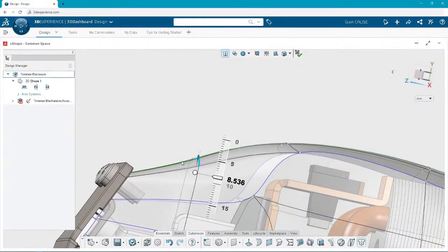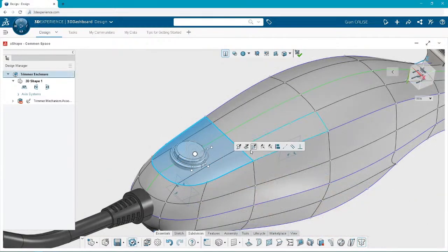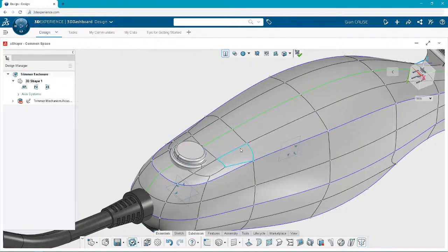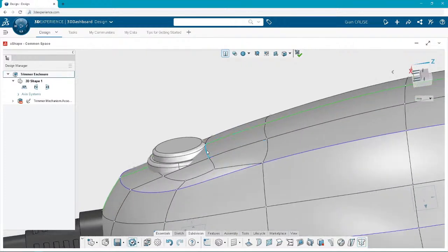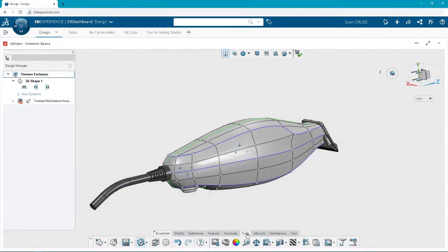Now, the next thing I want to show you is how you can get more localized control over a certain area in the model, and that's using the subdivide feature. The subdivide feature just takes these four faces and will split them into a new number of faces. In this case, I think it's going to be about 14, but this is where the term subdivision modeling comes from. It'll basically take an offset of the edges you selected and place those within. And then you can grab, control, push and pull those however you'd like to get that shape that you're looking for. And that'll help us stay organized with our power button.